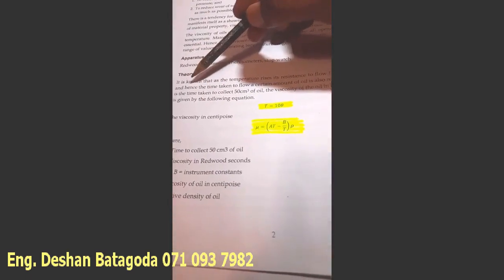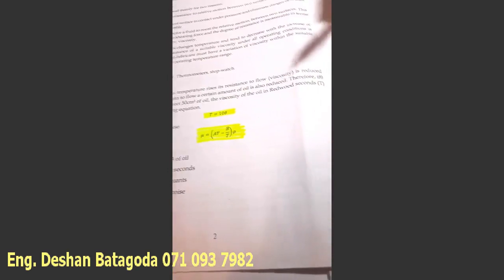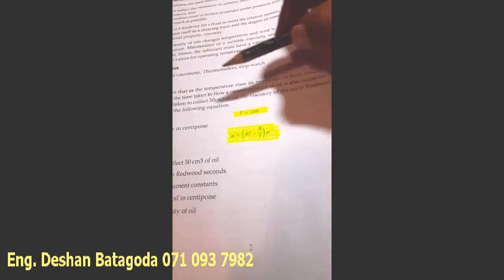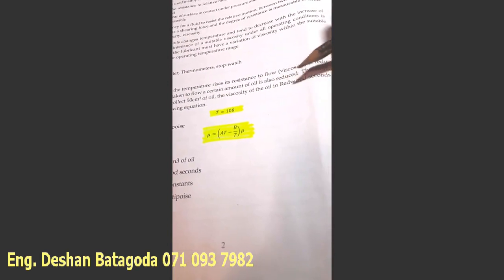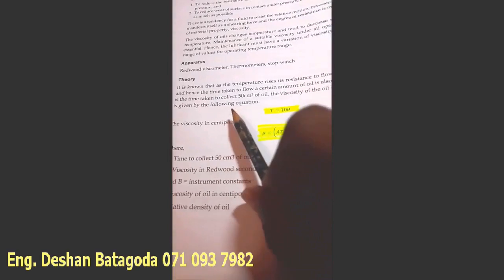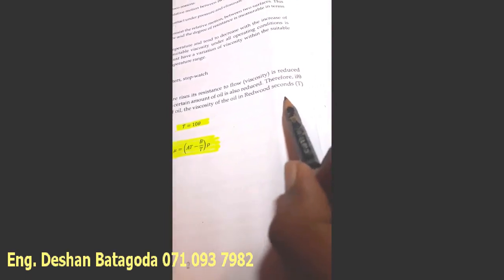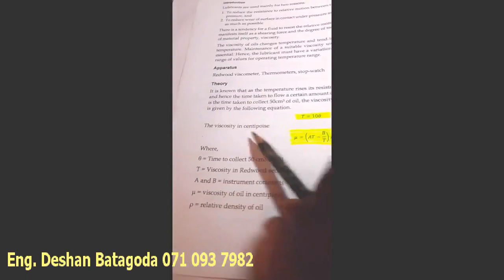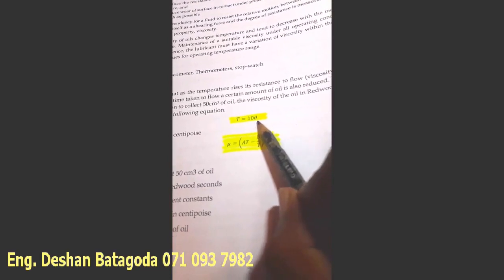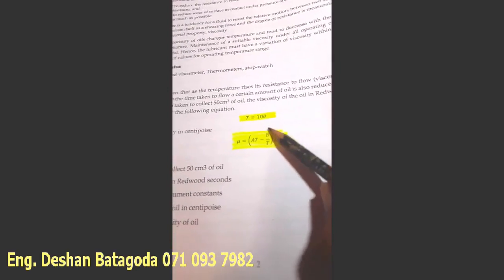Now just carefully read. It is known that as the temperature rises, its resistance to flow, in other words what we call the viscosity, is reduced, right? And hence the time taken to flow a certain amount of oil is also reduced. Therefore, if theta is the time taken to collect 50 centimeter cube of oil, the viscosity of oil in Redwood seconds, which we call capital T, is given by the following equation. Capital T equals 10 times theta, right? That is what we discussed under the Redwood viscometer practical.